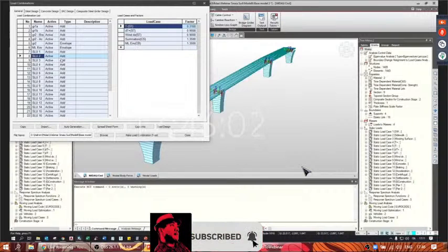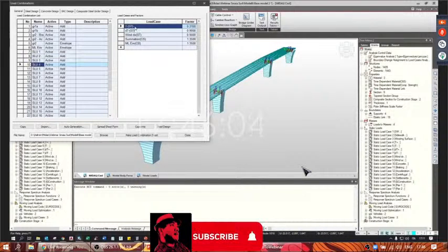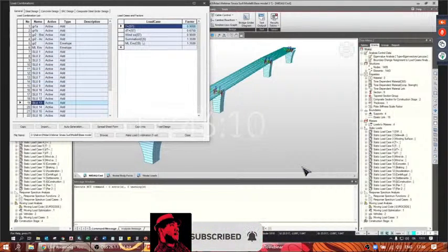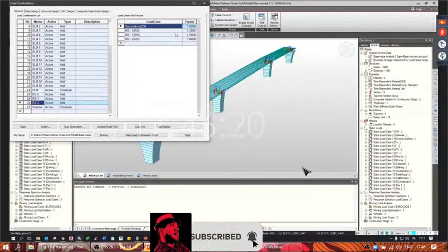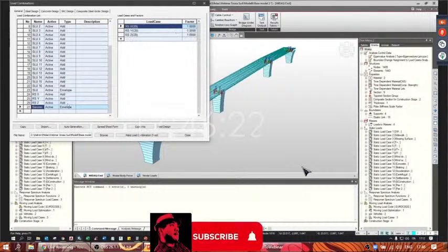We have, for example, the combination of the thermal loads here, combined with wind in both directions, and with the traffic and the summation of the stresses of the construction stages. Then we have the seismic combinations for the three main directions, and the envelope of all seismic combinations.